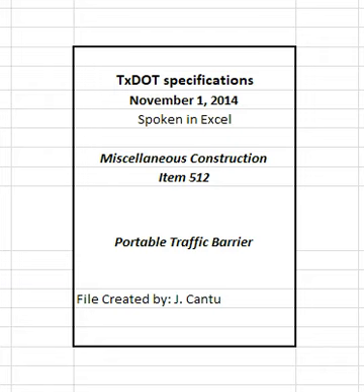Multi-project fabrication plants as defined in Item 424, Precast concrete structural members, fabrication, that produce concrete traffic barrier, except temporary barrier furnished and retained by the contractor, must be qualified in accordance with DMS 7350, Qualification procedure for multi-project fabrication plants of precast concrete traffic barrier. See the department's MPL for approved fabricators.